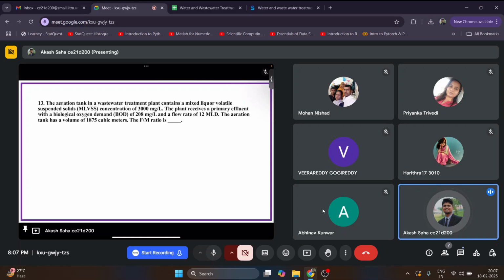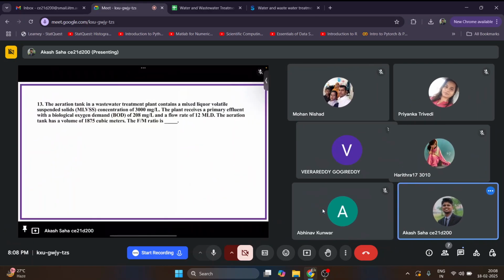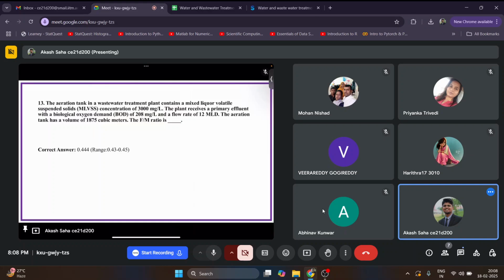What is the formula of F by M ratio? Can someone tell me? 0.44 per day. Okay, let's see the answer. So that is the correct answer. But it should not be in per day. F by M ratio doesn't have any units.